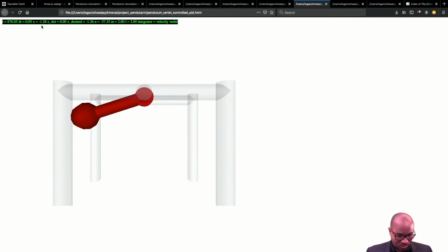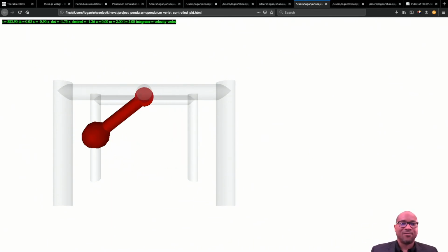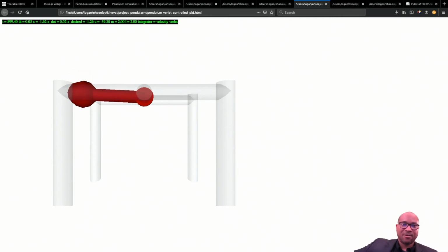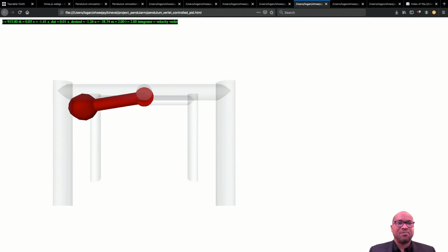And so once I have that, I'm going to let it swing for a little bit, and then I'm going to bring it back. And so you note that my system overshoots and then comes back down to the actual right amount. And so probably what's happening in this case is my proportional term, my integral term might be a bit too high. But I'm able to hit the desired target in reasonable time. Definitely not great time. And so I've seen much better examples of this. My other reference code has better examples.